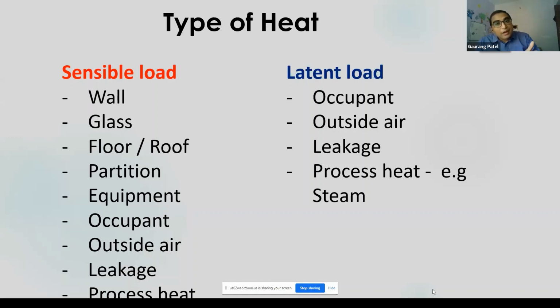And second is the latent one. The latent load is the load which adds moisture into the room. Because as a basic, for any comfort area we need to maintain two parameters: one is temperature and one is RH. And being a Mumbai guy, you know very well the impact of moisture there. I was from Ahmedabad, where I had seen temperatures of 45-47 degrees, but we have a low moisture rate there.